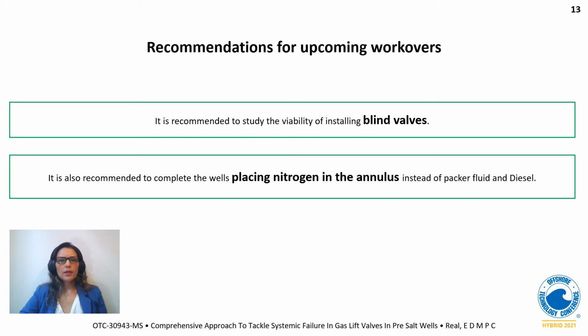It is also recommended to complete the wells placing nitrogen in the annulus instead of packer fluid and diesel. Thus, in case of gas lift failure, the contact between the packer fluid and the produced fluid can be avoided. Also, due to the expandability of the gas, it would be easier to maintain the pressure inside the annulus.